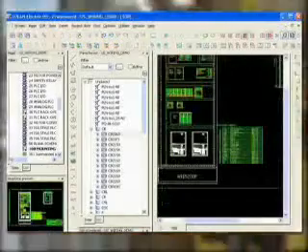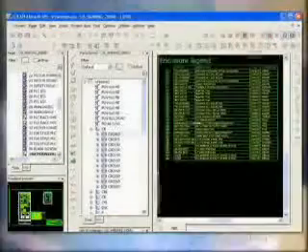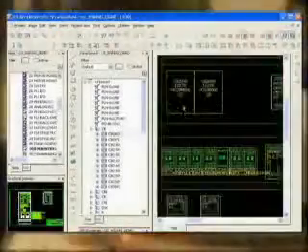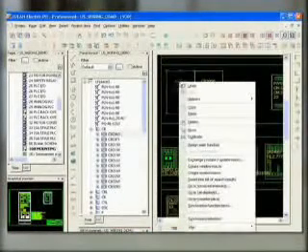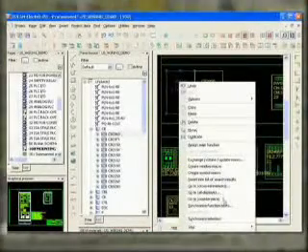An enclosure legend can also be generated automatically from the Reports menu. To jump back to the schematic from the panel, select Go to Counterpiece on the component.